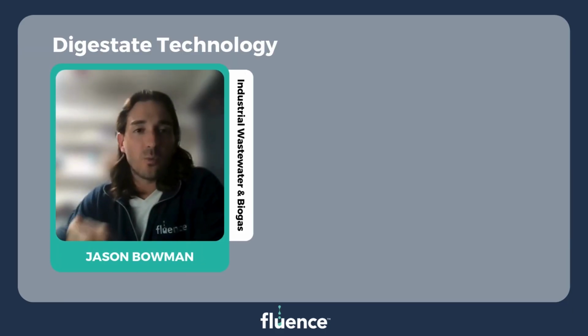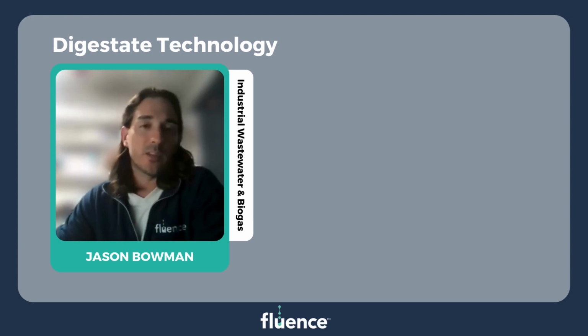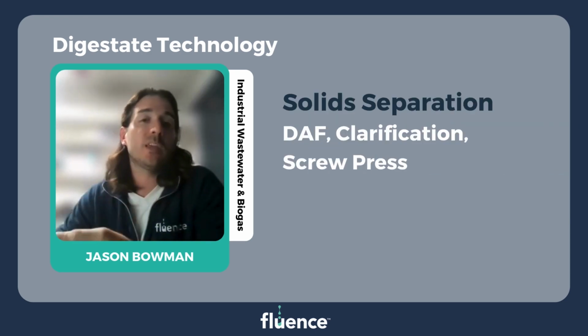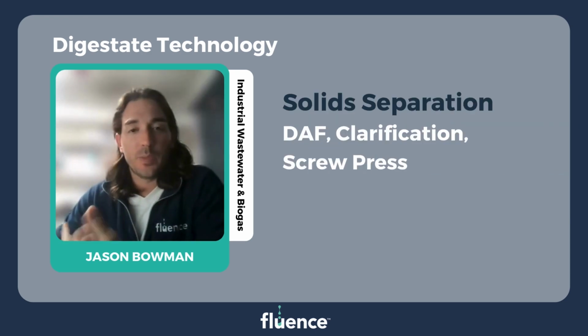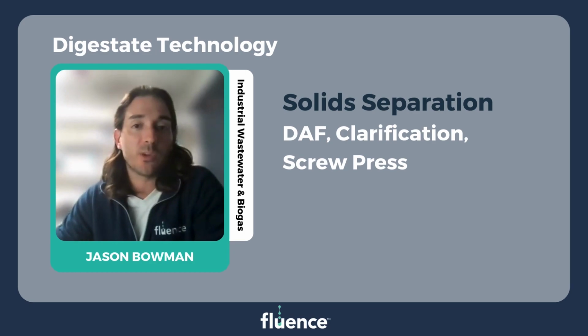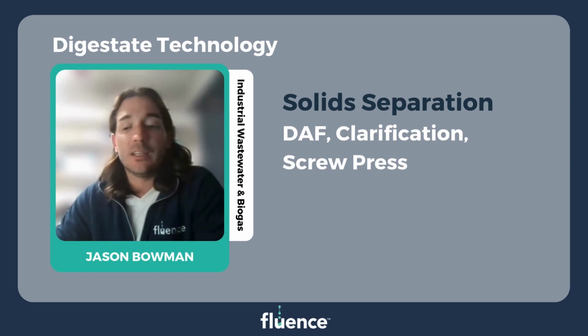Okay, so we have made it. Finally, we can talk about the different technical options available. So let's go through one by one, and then we'll put each of these under a microscope on the next few slides. So let's start with DAF, clarification, and screw press. Pending the type of digester that's being utilized, it's common to have a digestate with a total solids ranging from 30,000 to 40,000 milligrams per liter on the high side. So in other words, that's basically 3 to 4% solids.